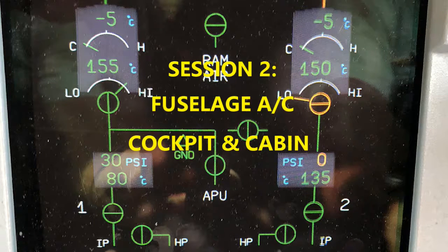And as far as the air cycle machine, obviously you have one for each pack. The left one, which is 10 HM1, is located above the 191 KB panel. Remember, it's the same panel that acts as the air conditioning pack. And on the other side, it's above the 192 KB panel. Then of course you have reheaters. The reheaters are installed between the main heat exchangers and the condensers. Same area, right? Basically, all your components for the air conditioning packs can be accessed through those two panels I just mentioned: 191 KB for the left, and 192 KB on the right. So just know 191 left, 192 right, and most of your components you can access through that panel.